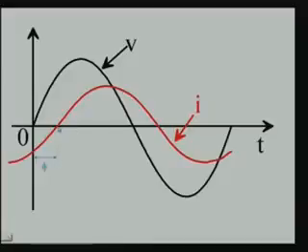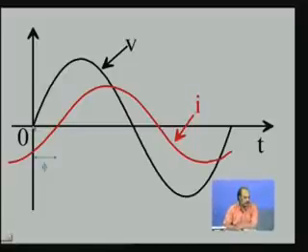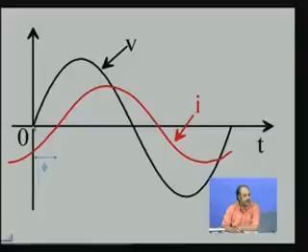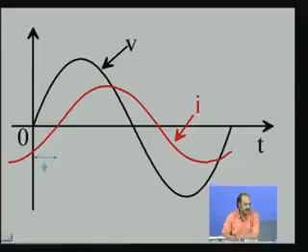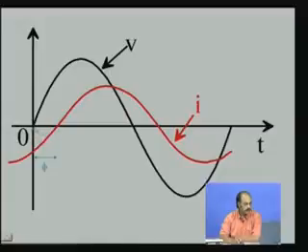If the current waveform were in phase at 0 with respect to the voltage waveform, then it would have been a pure resistive load. And if it had been exactly at this 90-degree point, then it is a pure L load. And if it had been exactly leading by 90 degrees somewhere here, it would have been a pure C load. Now, this zone from 0 to 90 degrees, any current waveform corresponds to an equivalent RL load. So, let us take an arbitrary RL load like this